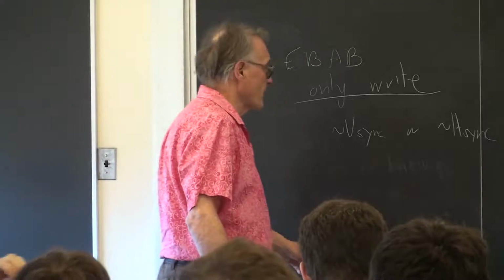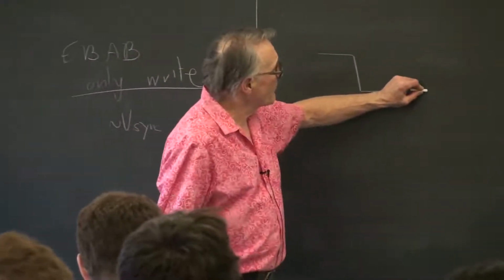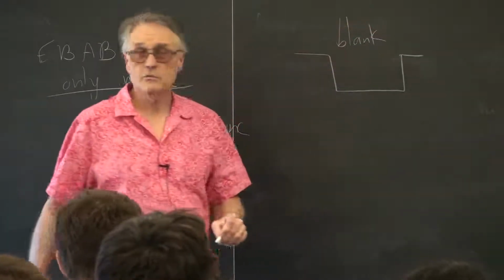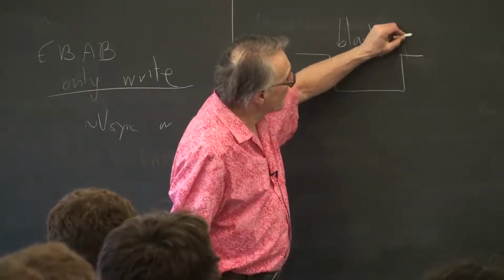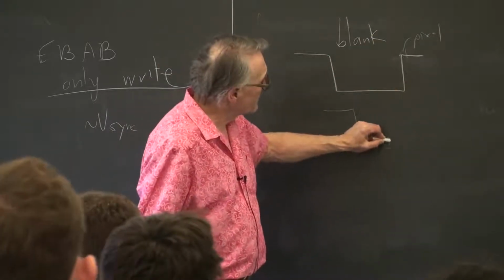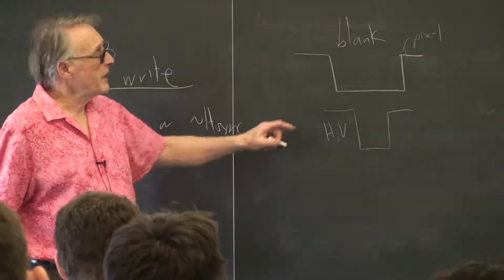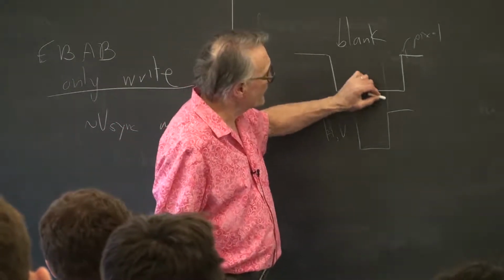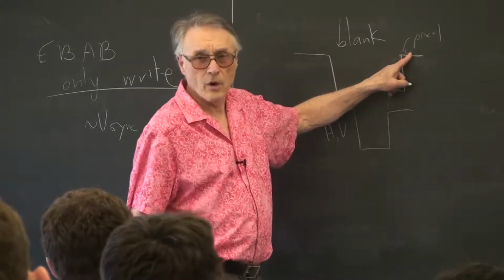And the timing diagrams, which you can look up online, show a V blank pulse during which nothing is shown on the screen. And the very next cycle, you draw a pixel. And embedded within that blanking period is an HSync or VSync. And because the H or VSync is shorter than the blanking interval, you have enough time after this to finish the write before the first pixel is required.